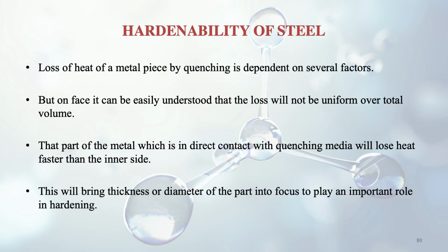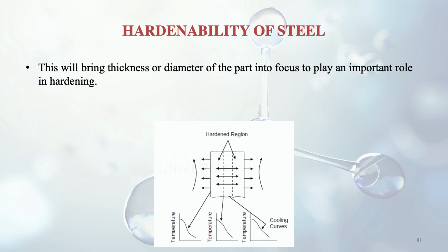So this brings the thickness or the diameter of the part into focus, because if it is a very thick object, then the heat loss from the inner part will take a lot of time. So the thickness or diameter of the part plays an important role in hardening.